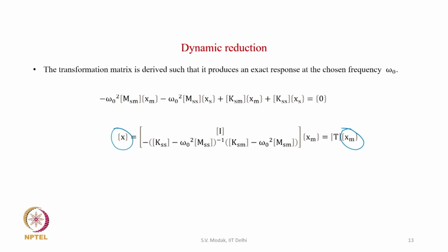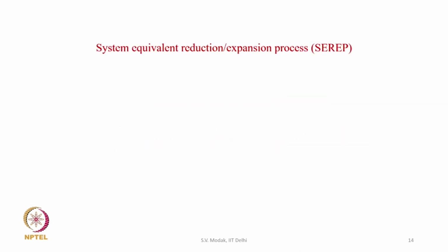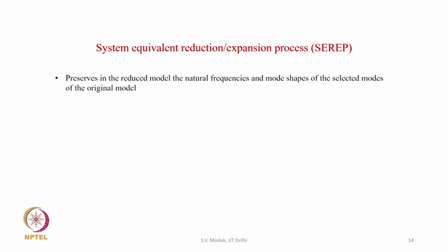Now, these two techniques do not preserve the frequencies and the mode shapes of the original equation. They would undergo some change because of the modal reduction and the approximations being carried out. So, another technique for modal reduction was developed whose objective was to preserve the natural frequencies and mode shapes of the selected modes in the reduced model, and that technique is the system equivalent reduction expansion process, which is abbreviated as SEREP.